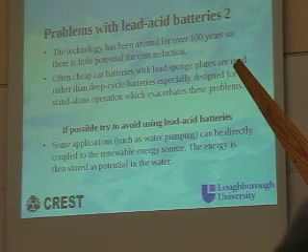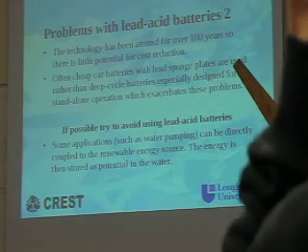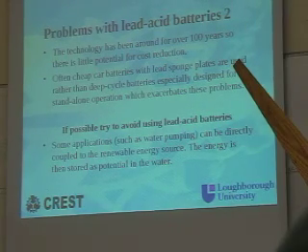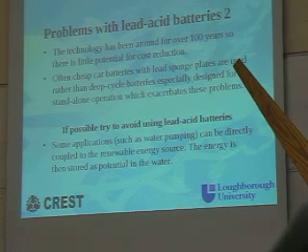Firstly, you should use deep cycle batteries. You have to use them, otherwise car batteries will fail very quickly. They're not designed for pushing energy in and pulling it out many times. If possible, don't use batteries. So the water pumping system I showed doesn't have any batteries in it. It's storing energy in the form of pumped water, and that's a much more reliable system.